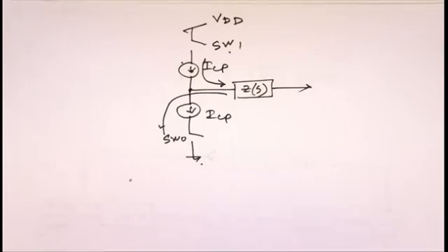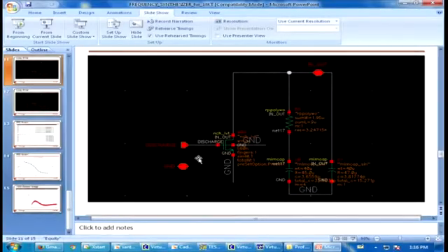Of course it's not possible to tell everything about the filter. And this is the loop filter, as I told. See, there is a discharge path I have made, because if something goes wrong, I can reset the loop filter by discharging it manually. Otherwise, this is a second order loop filter. We did this last night, just for a demonstration case.